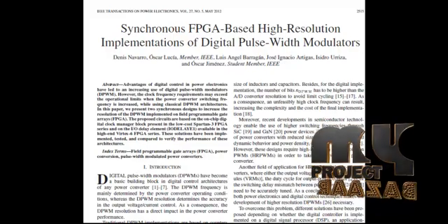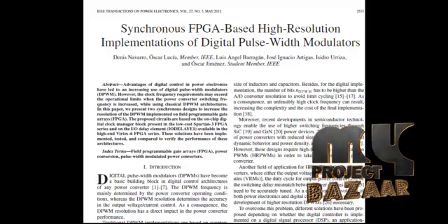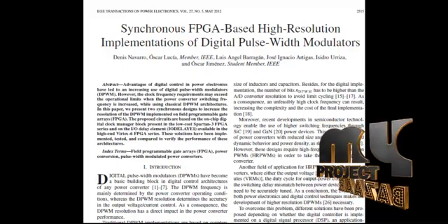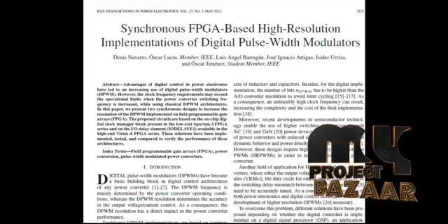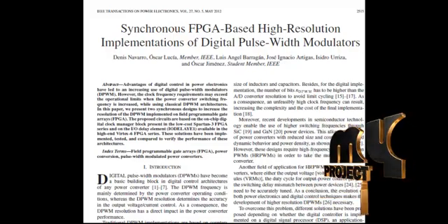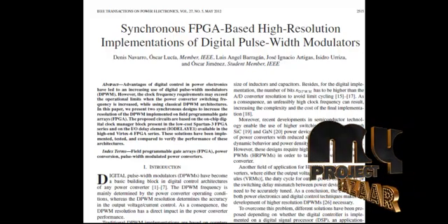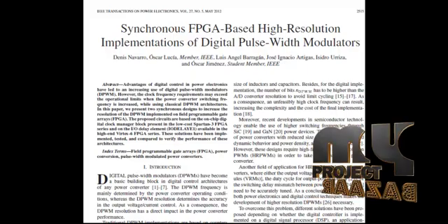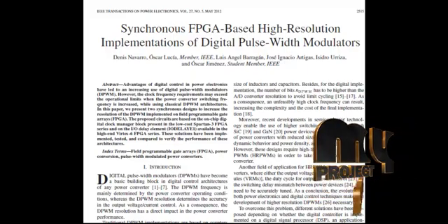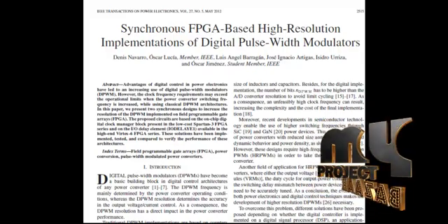Traditional digital pulse width modulators are based on counters. The advantages of these modulators are that they are very simple and attain high linearity. However, their resolution cannot be very high, as the minimum time step is equal to the clock period of the counter. Furthermore, their power consumption is proportional to the clock frequency, resulting in high power consumption. In order to increase the digital pulse width modulation resolution, delay lines can be used.